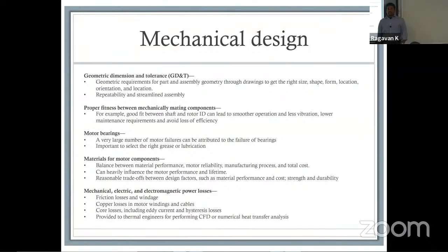You also need to have repeatability and streamlined assembly. If you don't do that, then taking it to commercial production will create major problems. We have to design a system that is not meant to be so high or so strict in its tolerances that manufacturing requires very specialized equipment. That will increase the cost.